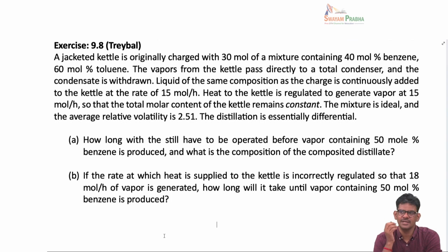We have to go to the material balance problem. Again, we have to write how many moles are coming in, how many moles are going out, what is the accumulation with respect to the total moles, with respect to the species, and then set up a new mass balance equation for this particular problem, and hopefully you will get some expression that will show some time dependence in the composition. Okay, so that's the strategy.